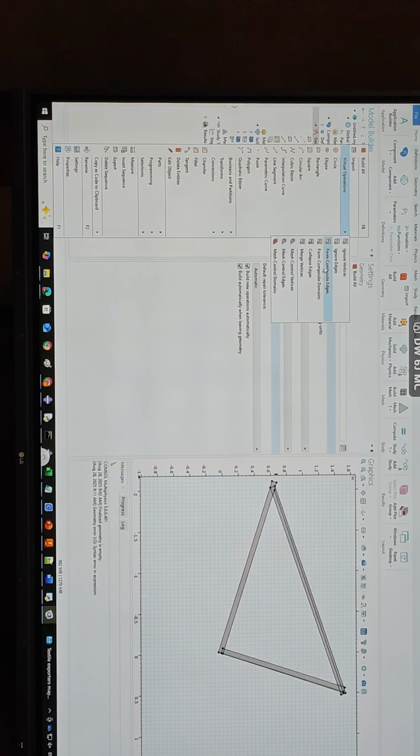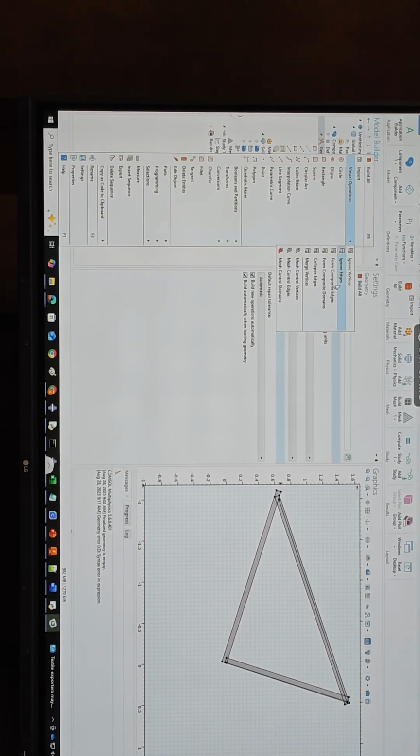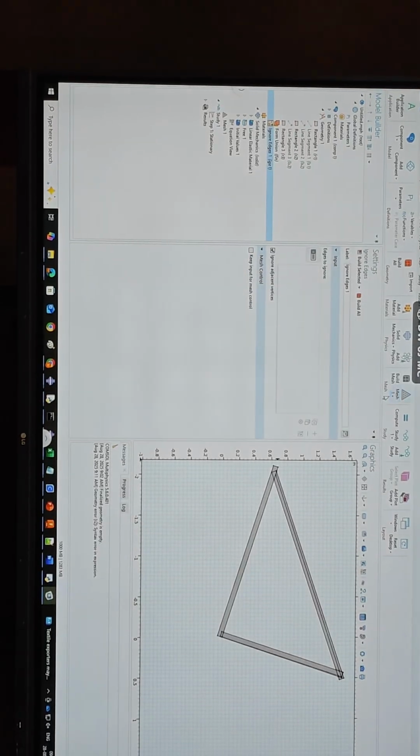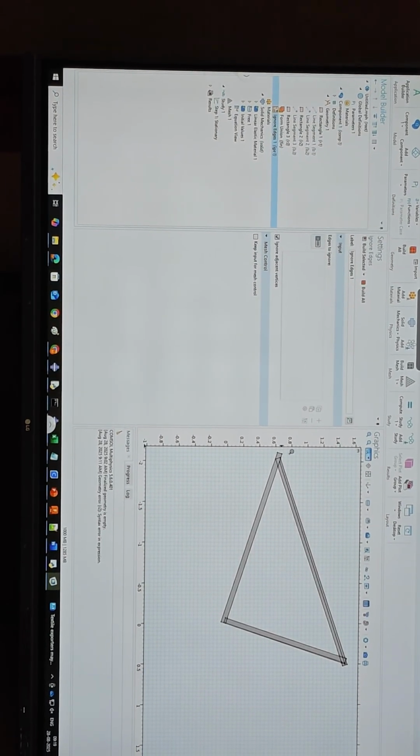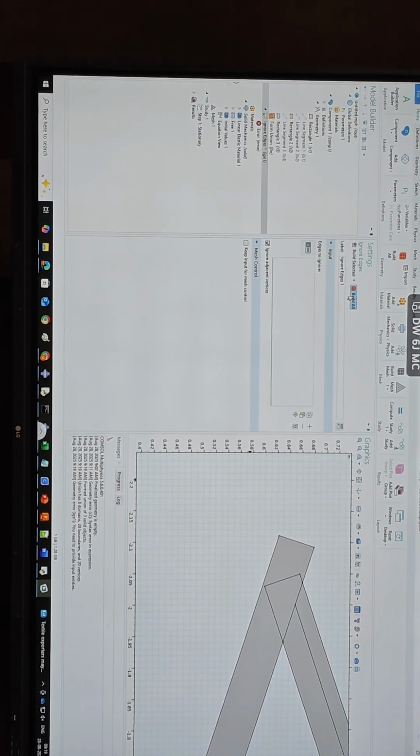So we can go now to the geometry, right click it, go to virtual operations and ignore edges. You click the ignore edges option. Now I'll disable this line segment which was previously created, both of them. So disable. Disable. Now in ignore edges, I will use the zoom tool and zoom in on each of these connections. If I click build all, it should remove that line.